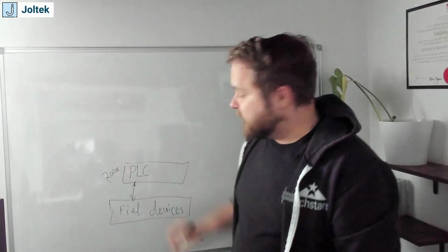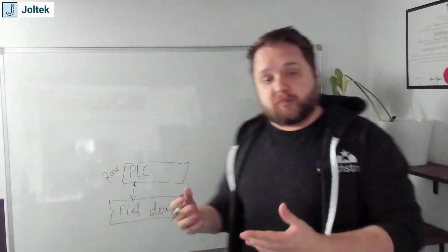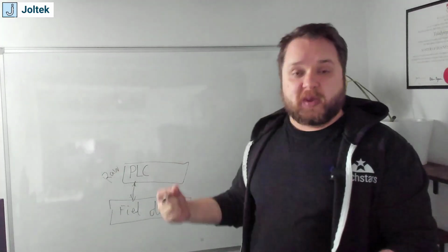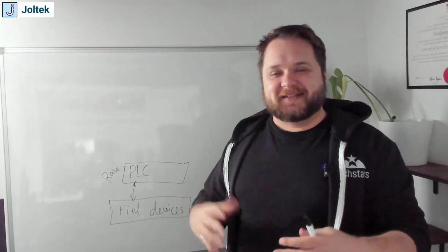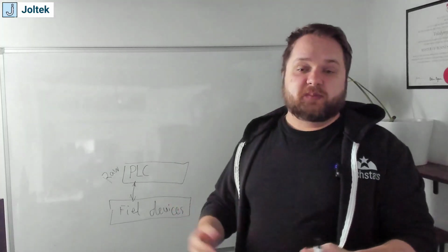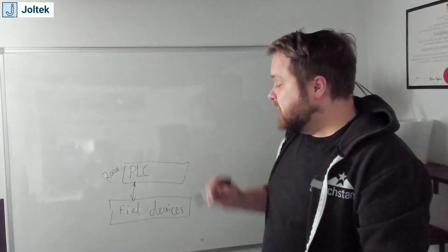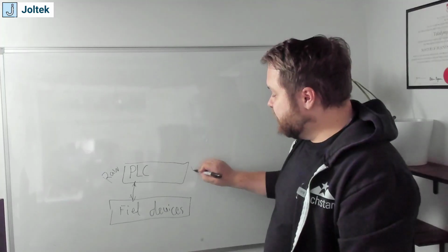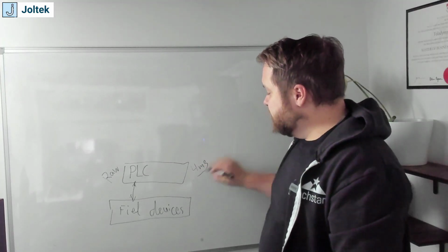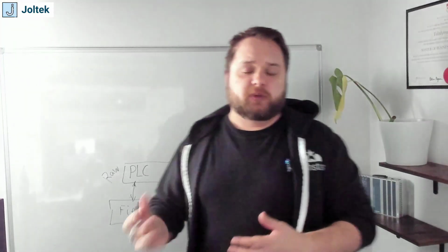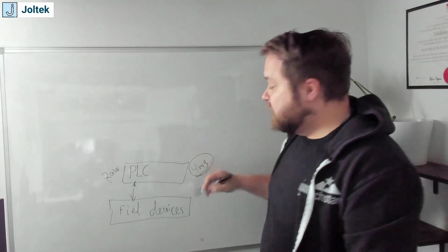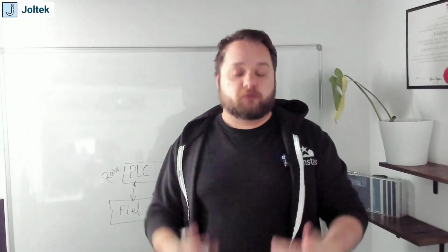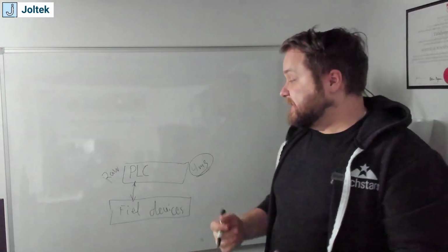I've described this in a lot more detail in the previous video, but ultimately this is where raw data is going to reside. Raw data just means that the PLC is extremely fast, so it's going to be picking up those signals every scan cycle. Again, there's a lot of discussion to be had as to when the PLC picks up and updates inputs and outputs, but ultimately imagine that every 4 milliseconds or so, depending on the system, it could be lower or a little bit longer, the PLC is going to update all the raw registers within itself.